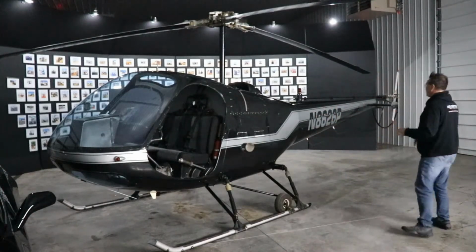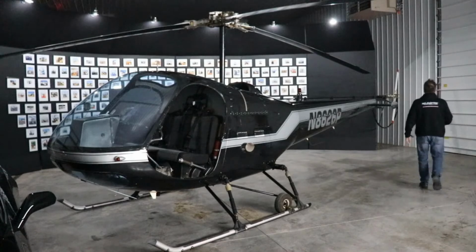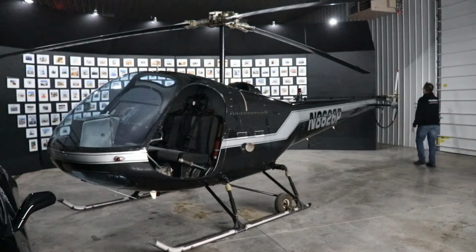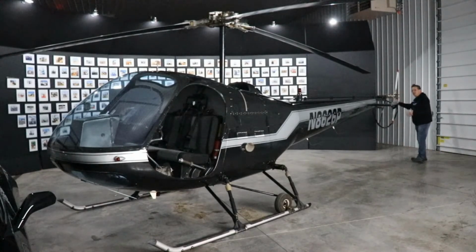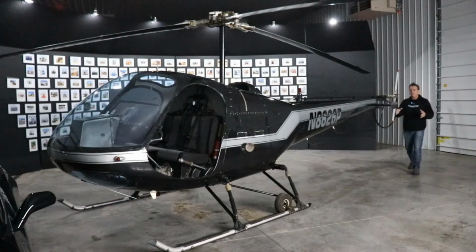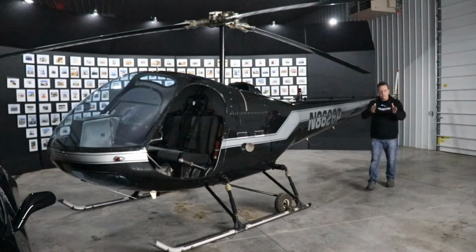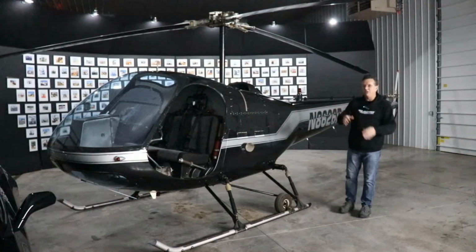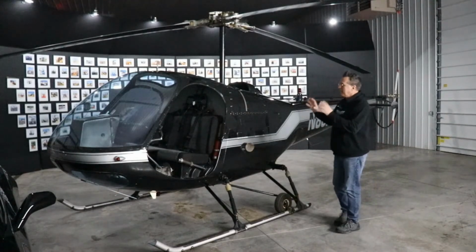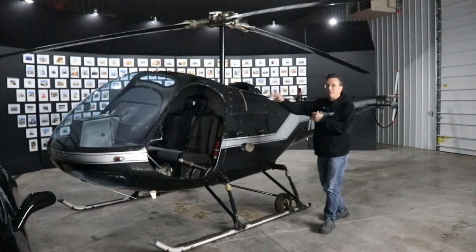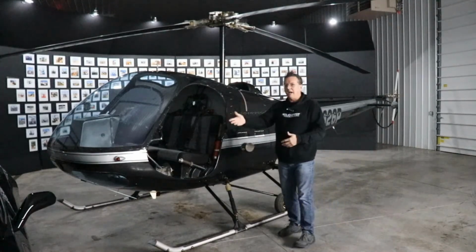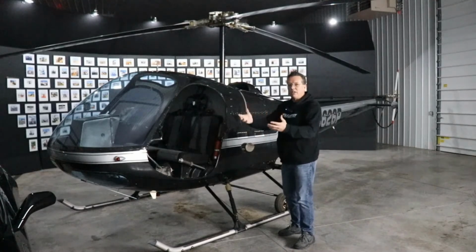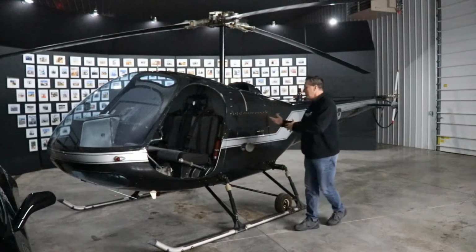In the section on helicopter controls, you are going to learn about how you use the pedals to operate the anti-torque rotor, or the tail rotor, and at slow speeds, you use those pedals to make adjustments with the nose left and right on the helicopter and control the nose of the aircraft. Basically though, when you get moving in forward flight, like say 60, 70, 80 knots, you then have what they call streamlining of the fuselage.